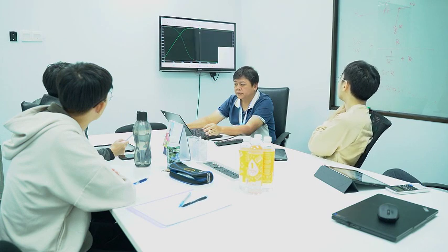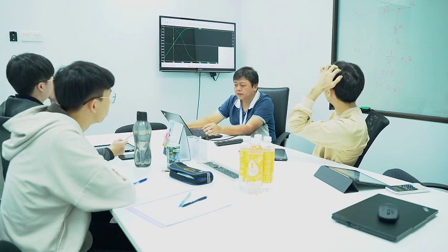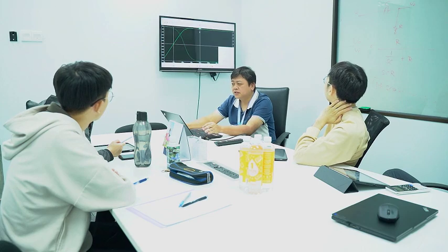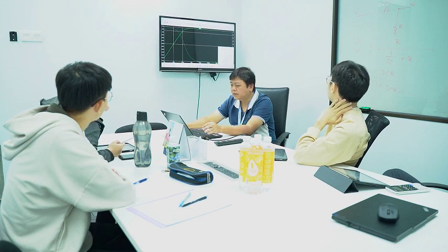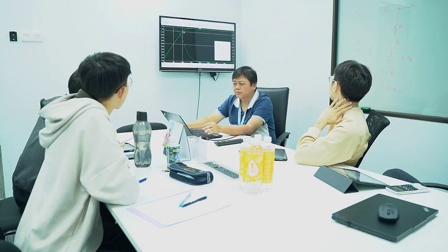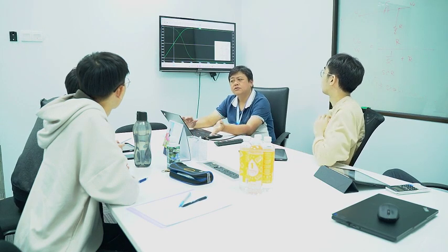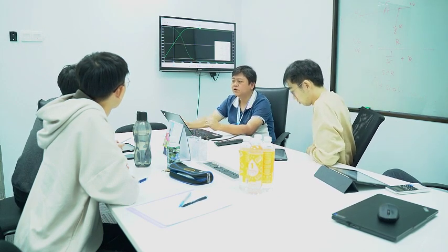You find the slope here for this one. What is the second curve behind it? The dotted one is the phase shift, right? So you find a slope here, but hopefully it's okay. It's about that, because it has almost already met the zero there, about 18 dB, 18.5. But if you put it here, lower a bit, you get 20 dB per decade, right? This is a zero with a 20 dB per decade slope. This is the first thing you want to learn here.